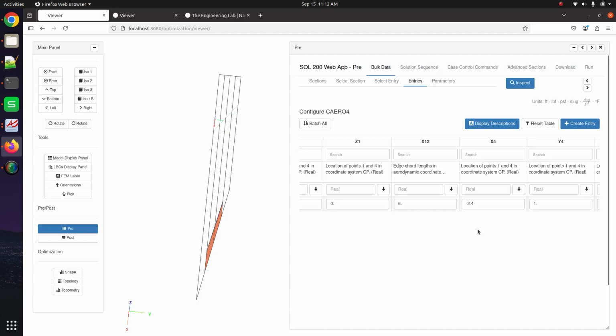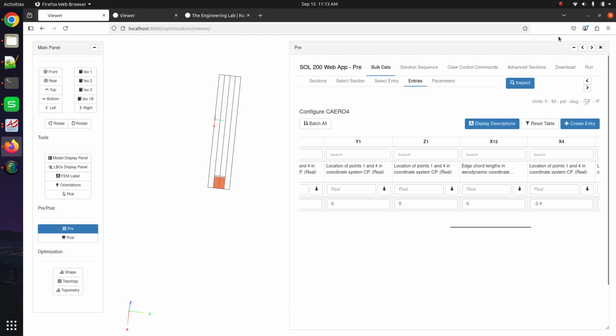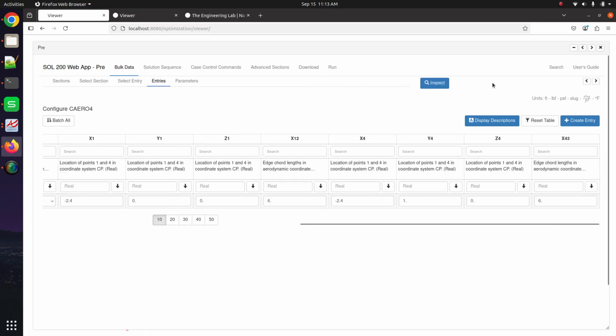And now suppose you want to use 5 strips. And here, just to confirm this configuration is okay for Nastran, you can click on inspect. This Nastran model was working before this exercise, so if I made a small modification, I expect the inspection to also work. If we look at the status message, it says complete. That means the Nastran model is okay.